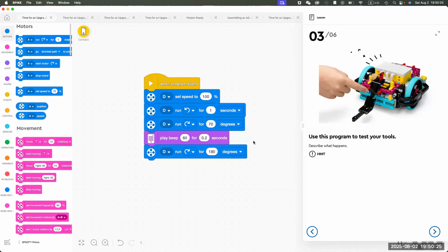Because if you keep it high and you want to adjust it, you don't know how to turn it higher by 5 degrees or 10 degrees, because you don't know where the position is. By keeping it low, you start from maybe 0 degrees, and then you can go counterclockwise 70 degrees, and you know where it will be positioned at that point. So starting from the lift arm being low is step 1, called reset.